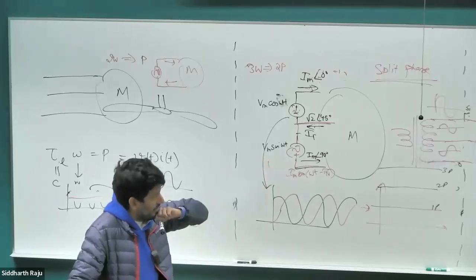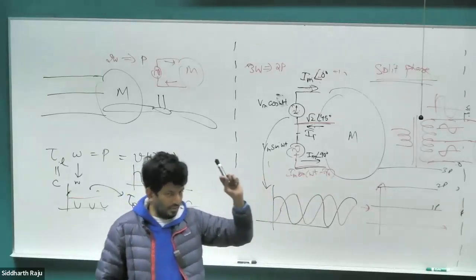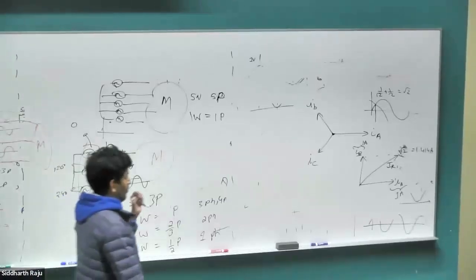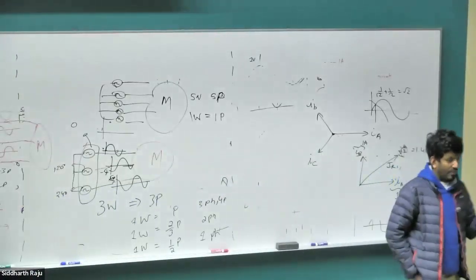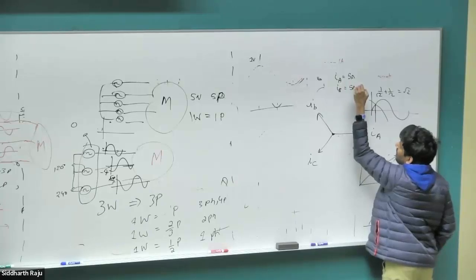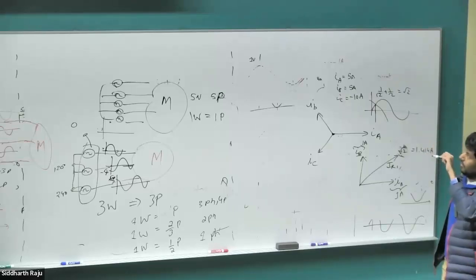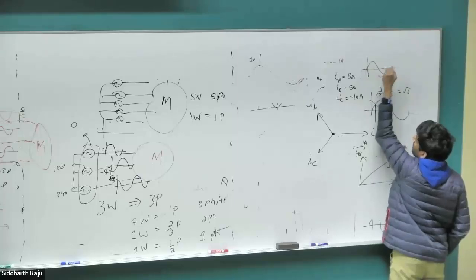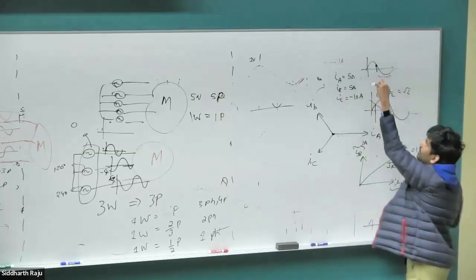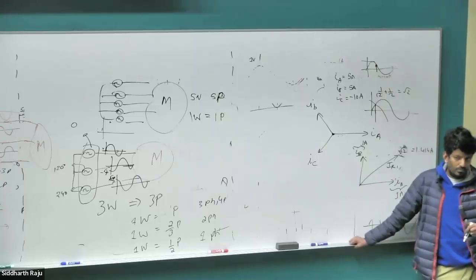Okay, can you tell me, let's say the case where I had 5 ampere, 5 ampere, minus 10 ampere, what would have been the magnitude of the phasor? The single phasor. If I give you a time instant value of current, if IA is 5 ampere, IB is 5 ampere, and IC for a three-phase system is minus 10 ampere, and I ask you what will be the magnitude? So this is at one particular instance. I had some current like this, and I took a snapshot somewhere here, and I gave you the three currents for three different phases. Can you tell me what the peak of the currents would be? Is it 10? 10 ampere.